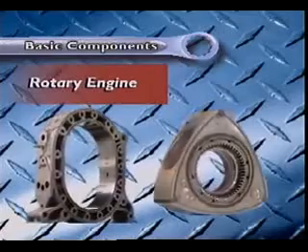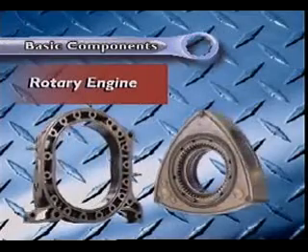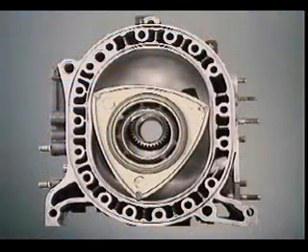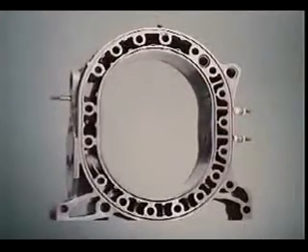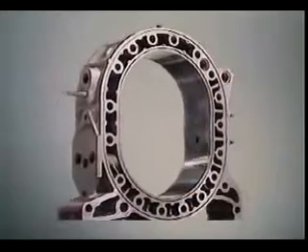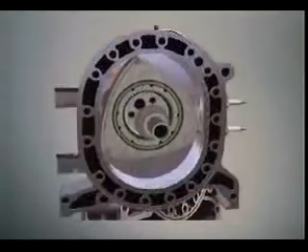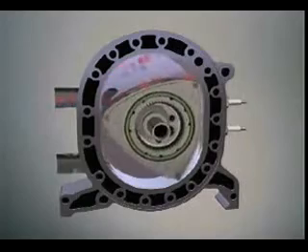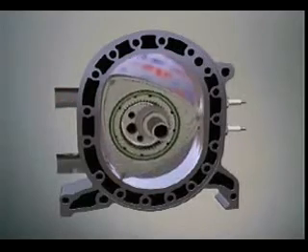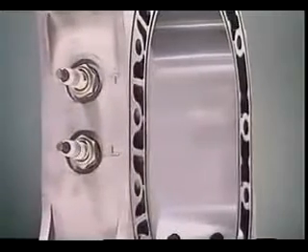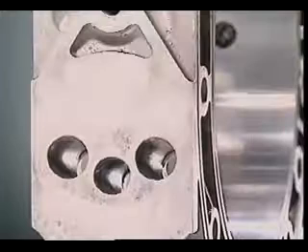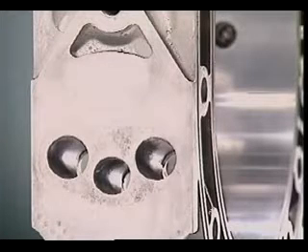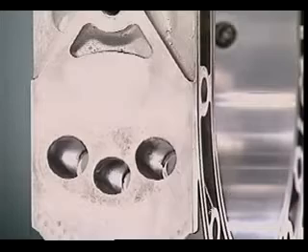Let's look at the rotary engine's major parts. The rotor is mounted in an oval-shaped housing. The housing is made of aluminium alloy, but the curved surface has hard chromium plating. This surface has to put up with the wear and tear of the rotor sliding against it as it turns in the housing. There are usually two spark plugs fixed to the housing which enable combustion to occur. The rotor housing also has an exhaust port to expel burned gases. It has cooling passages for water to circulate.